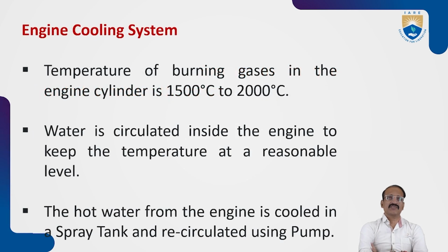Engine cooling system. The temperature of burning gases will generally be from 1500 to 2000 degrees centigrade. So we have to circulate water. Water is circulated inside the engine to keep the temperature at a reasonable level, otherwise it will probably melt.